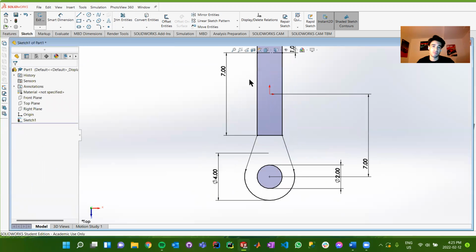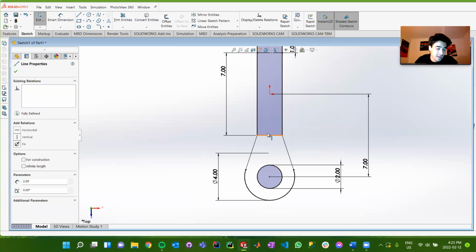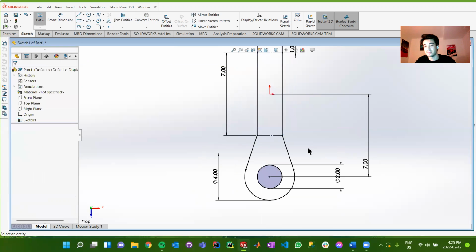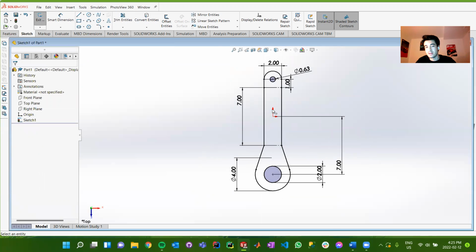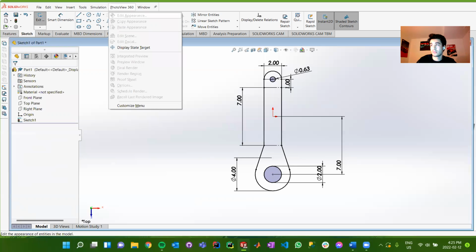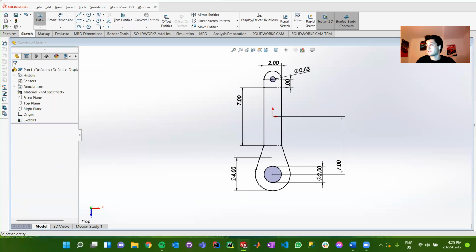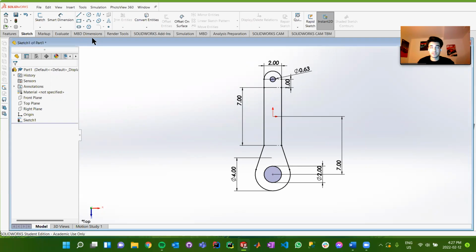And you'll also notice that we've already established a dimension with this existing line, so I don't necessarily want to get rid of it. So what I can do is keep it as construction geometry like we did above. And then from there, we essentially have this shape. Now you'll see it's got 2 different contours that are shaded as so, but trust me, when we extrude, which we'll do right now, it'll all look like it's coming together. Cool. All right. And then from there, we're essentially good to extrude. So we can do that as such.